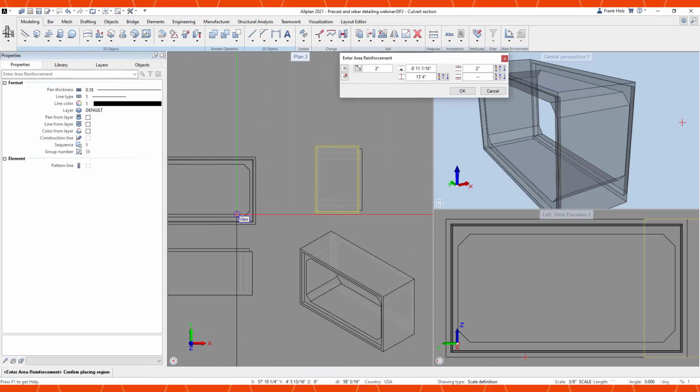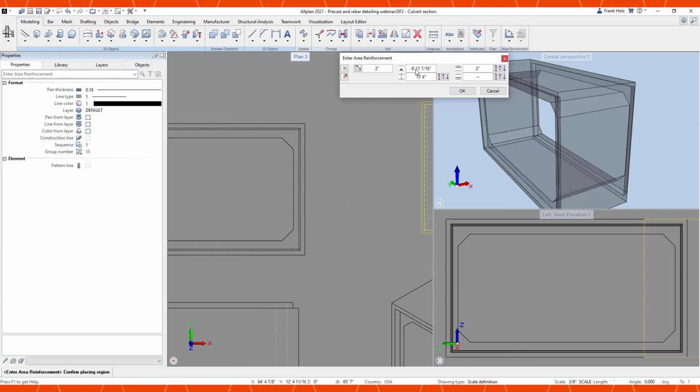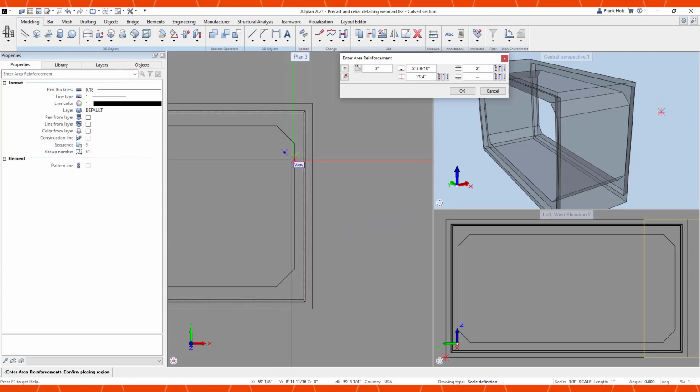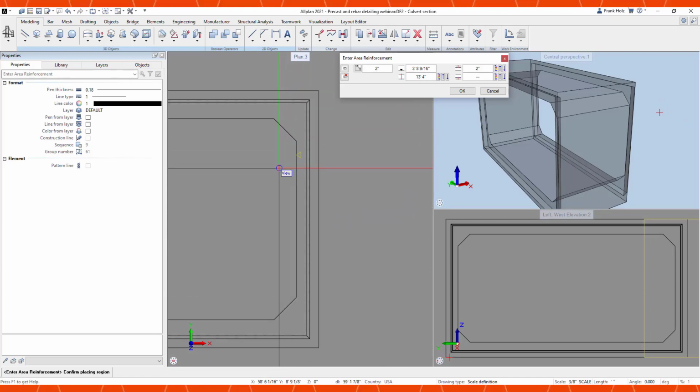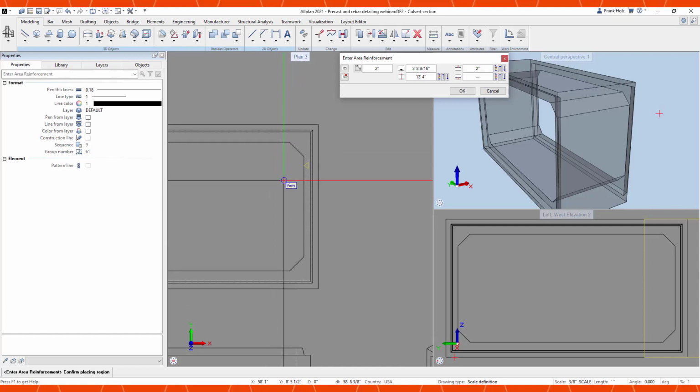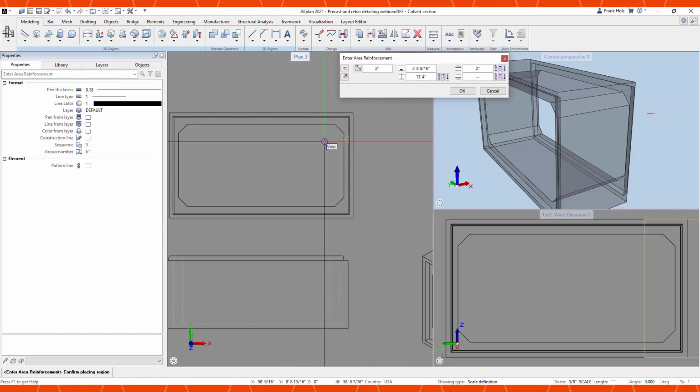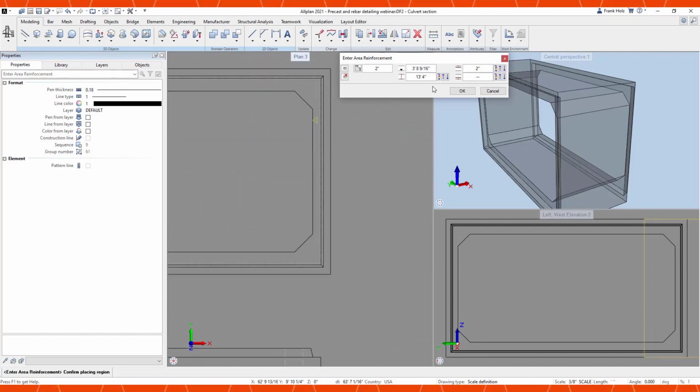Now in Allplan, whenever you have to enter any values, so here I have to choose my X position, I can actually just click on screen. It's going to read that value and actually show me a little heads up arrow of where I clicked to let me know that I've locked in right at the base of that slab or that wall. Now for choosing the member thickness, you can see it found the full extents. I just want to correct it and say we're doing a single wall here. And so I can simply click 2 points. Allplan's going to measure the distance between them and then use that as my component thickness.